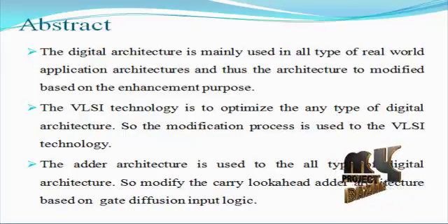In this paper, the GDI technique is used for low power design of an 8-bit multiplier. Reduction in power and area can be achieved using Booth encoding and the Wallace tree technique, since they generate partial products efficiently and are most suited for multiplication of signed and unsigned numbers. Multiplier design with GDI logic requires fewer devices compared to CMOS logic.